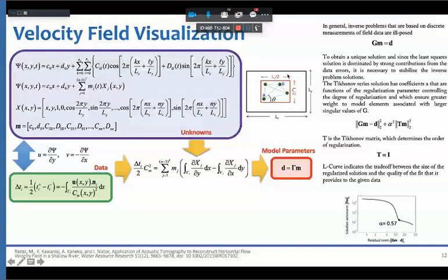So we're going to have to solve these particular equations. But remember that because the computational domain is larger than the physical domain, you might have some streamlines that just go through the boundaries, which is not acceptable. So what you're going to do is introduce some boundary condition. How are you going to do that? You're just going to set the velocity perpendicular to your boundary to 0. Whatever velocity, this is the normal vector at each location.